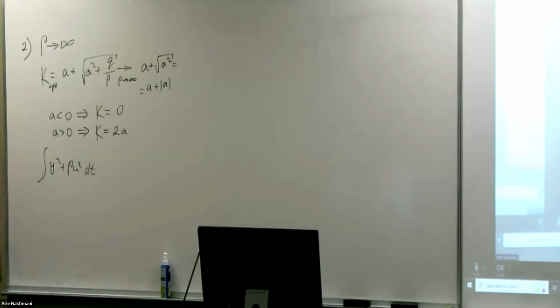X, whatever. What will be small if rho is huge? You're minimizing that thing. So you will penalize energy of the input. Because if u is larger than 0, this thing will be huge compared to this thing. So I want this thing to be as minimal as possible, right? To make it balanced somehow, to minimize that thing. So if I'm going with that up, u will go down, energy of u will go down, by the minimization process. So I'm penalizing high control effort.